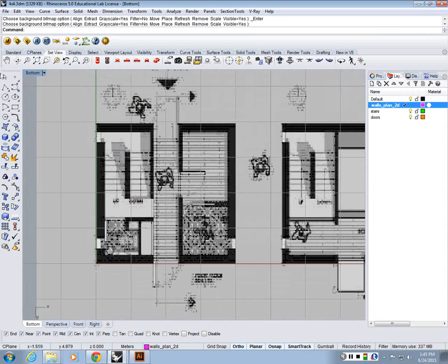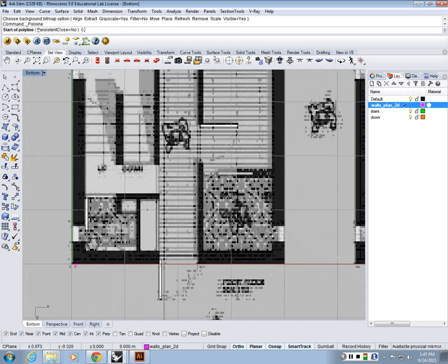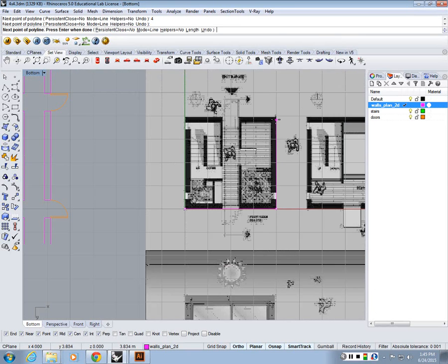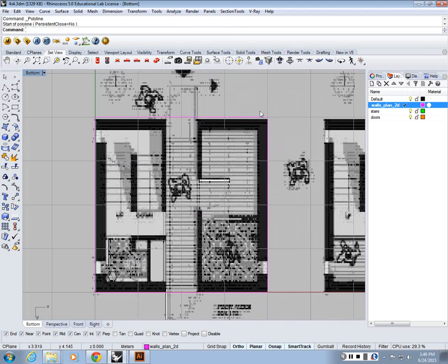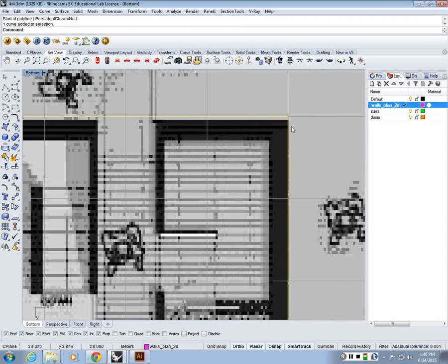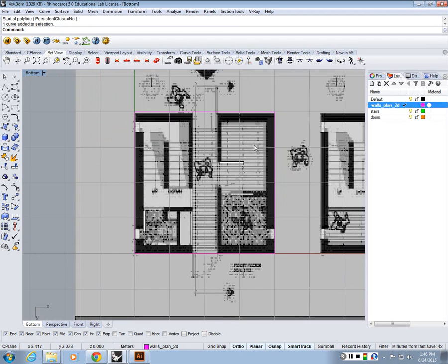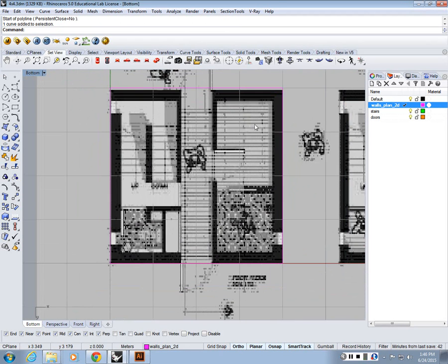And the way I started drafting it was basically started from 0, 0, 0 and then went by 4 to the right, left click, to the up, 4, left 4, and I can enter C to close. There's a function here to close the polyline, or I can just click on this point to close. It's the same thing. So now I got my outer wall. This is actually supposed to be 3.95, but I entered 4. It's okay.